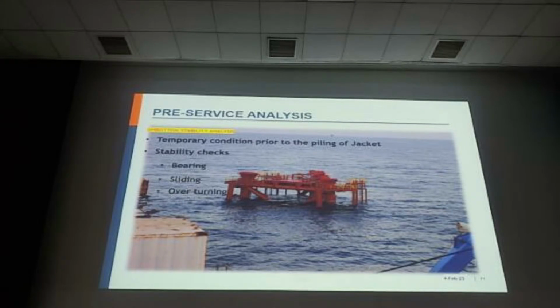Then on-bottom stability analysis. Once you launch and make it vertical, it should be stable. It should not move, or you will see some stability problem. It should not sink in, it should not slide, and it should not overturn. All this we have to study, otherwise it will not work out. We have to make sure that our structure is stable in the on-bottom condition also.